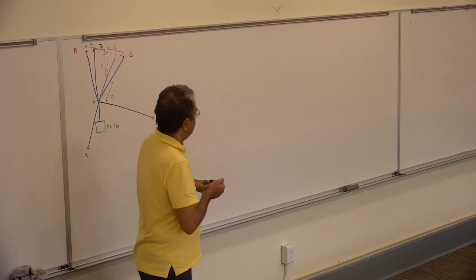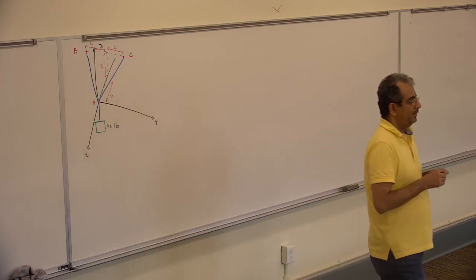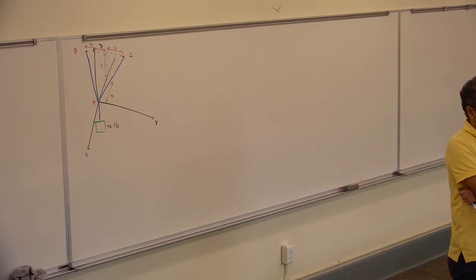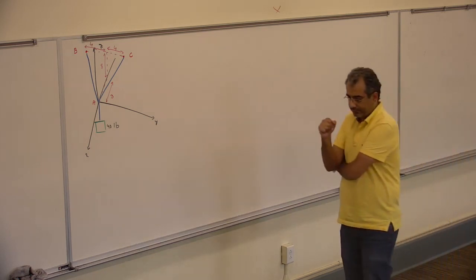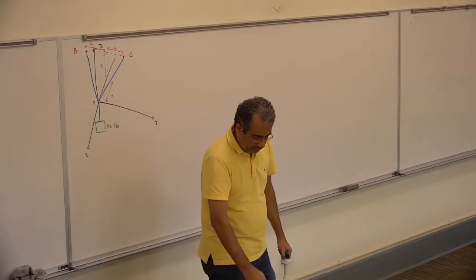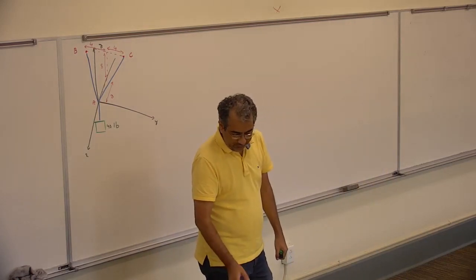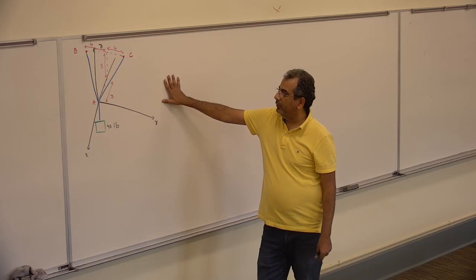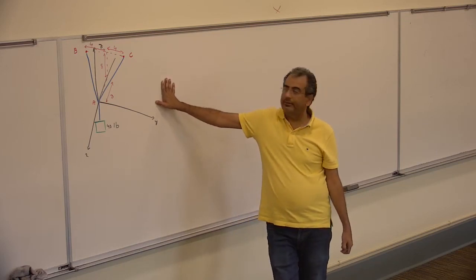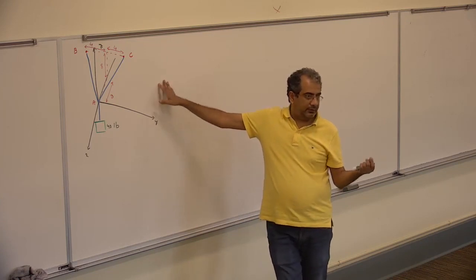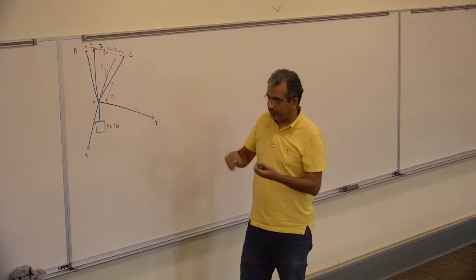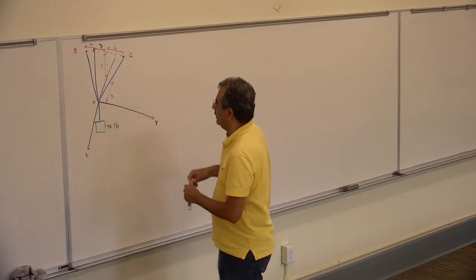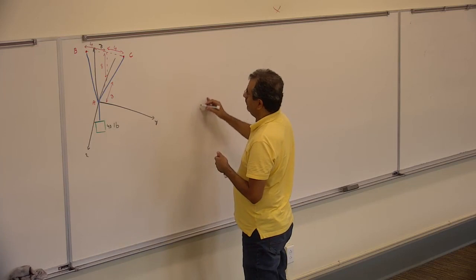So, remember what was the procedure? Draw the free body diagram, put all the forces on that, reactive and active, and then write them in a Cartesian format, and then write the equilibrium equation in the Cartesian format. So here, if I want to draw a free body diagram, what point would be the best to do that? Probably A. Yeah, the point A of the problem, because all of my forces are going to meet there. So you can go ahead and redraw that again.